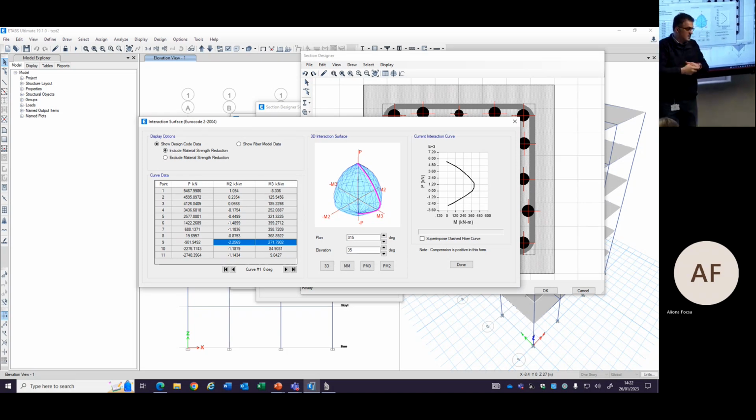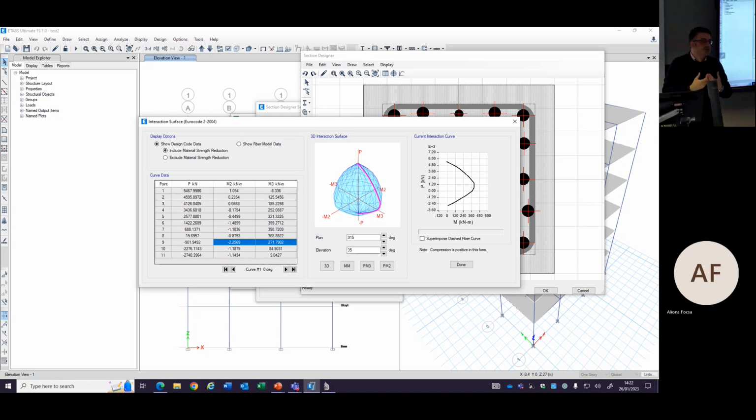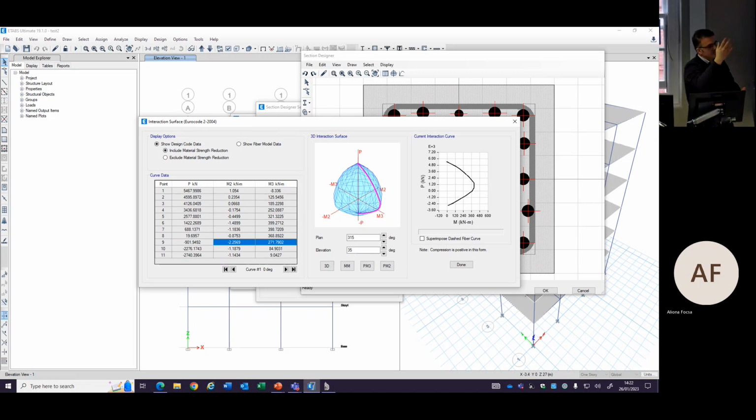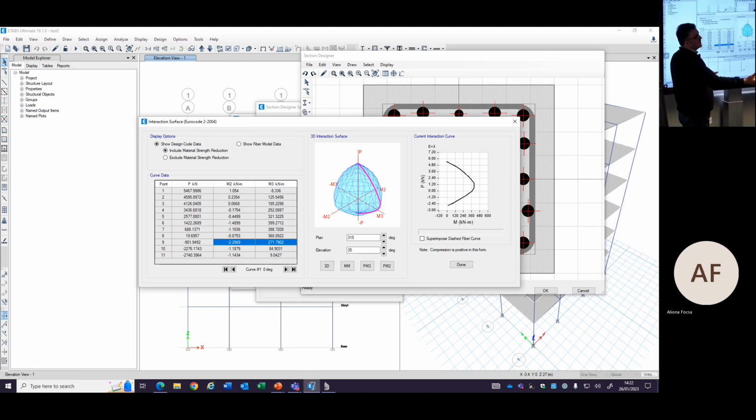This is important. The sequence is important, and you should understand what ETABS is doing when you get results like the demand to capacity ratio. The structural analysis gives you some internal forces. This is the capacity: this kind of reinforcement, this kind of geometry, this kind of concrete.